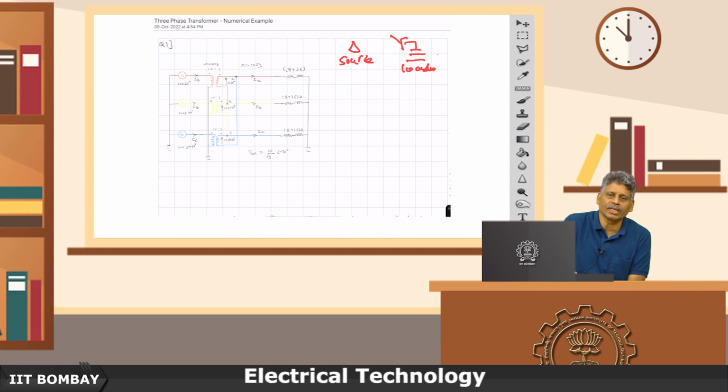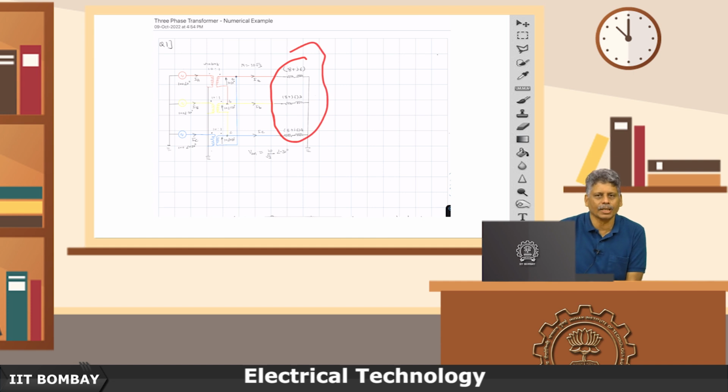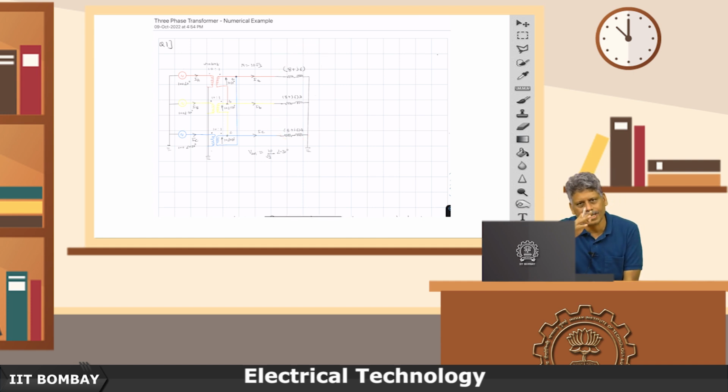So there are different techniques to analyze this balanced circuit. For example, I could do a star delta transformation, which you usually study in network analysis. You can convert this into a delta, and then I would have a line to line voltage connected to a line to line delta. That is one approach which I could do. But I would take a simpler approach.